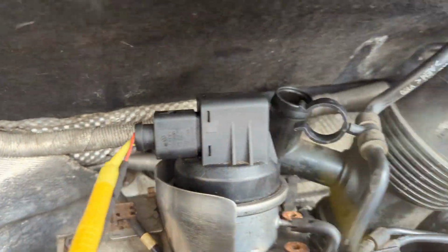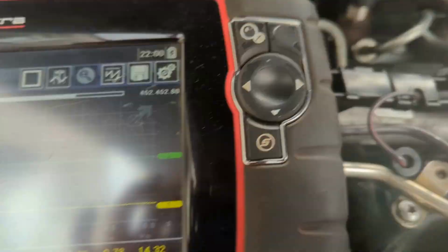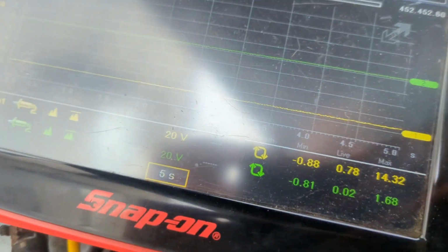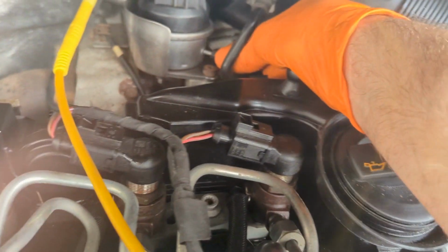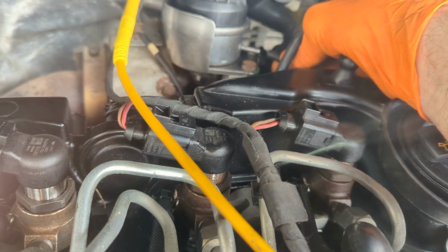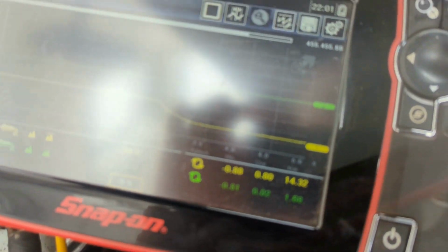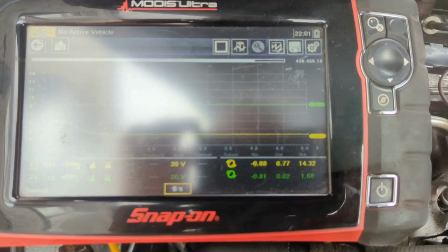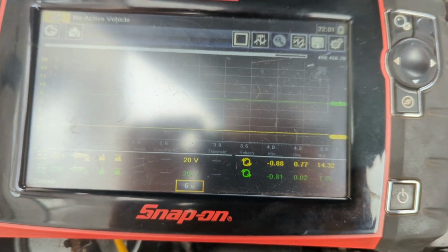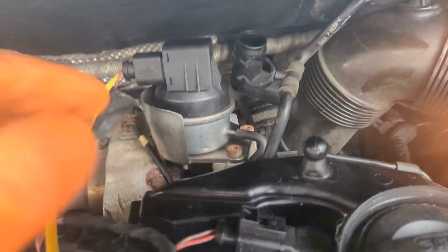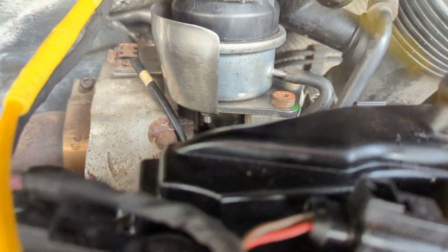Right, back in the signal wire now. Got vacuum on. We're on 0.7 of a volt. If I remove this, go up to 4.1, put it back on. Voltage drops to what I think should be acceptable. I'm going to clear codes and maybe try and road test it. These aren't secure yet. These lock nuts aren't secure yet. I just want to see if they're somewhere in the ballpark where we need to be.